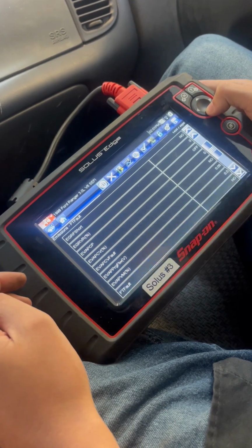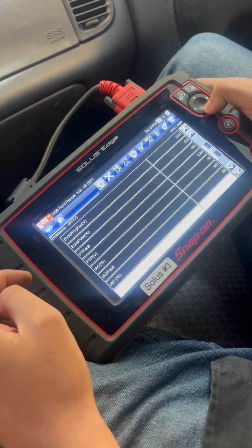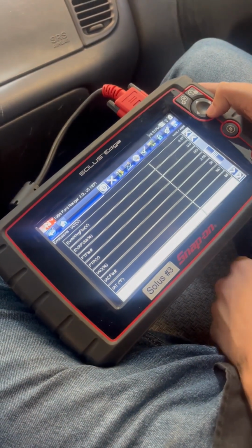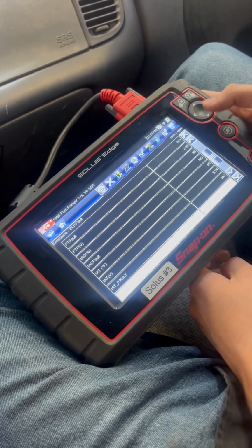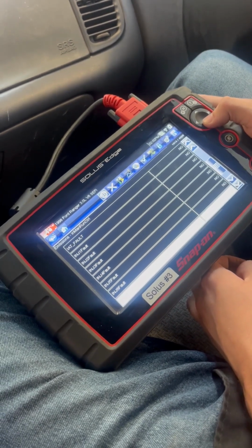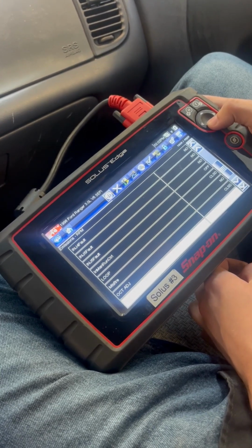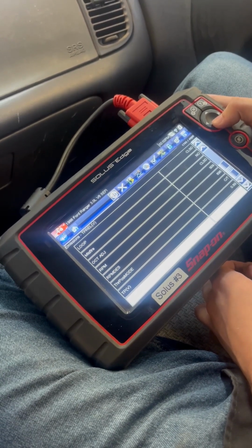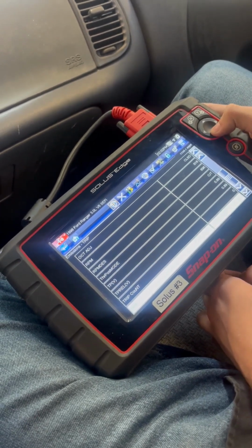We don't have any evap faults. We don't have any idle air controller faults. That is still running good. Our idle air temperature is 66 degrees, or 3.24 volts coming from that sensor. Our injectors are all good. We're running in closed loop, no misfires. RPM sitting at 900. Throttle position is at 0.89 volts, which is basically closed. That's where it should be.